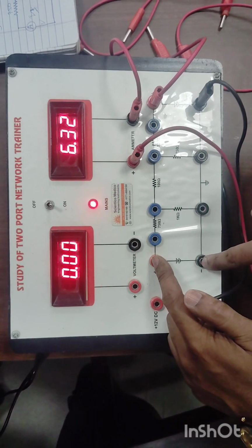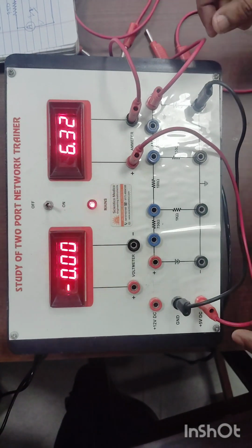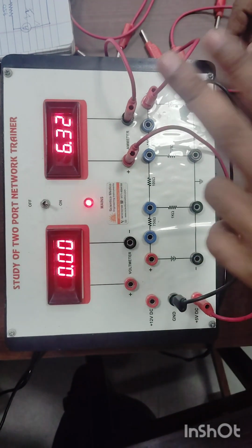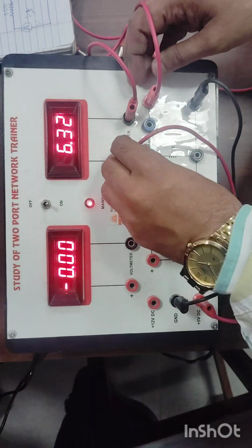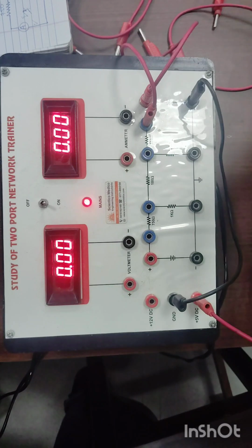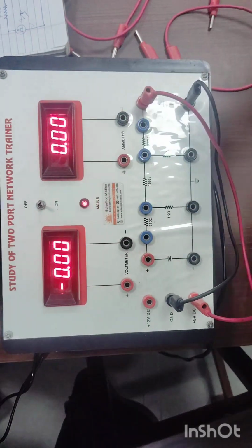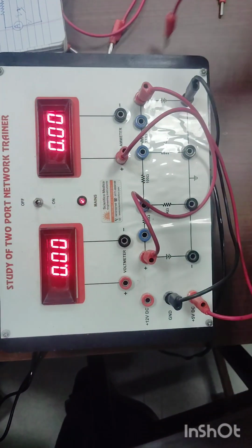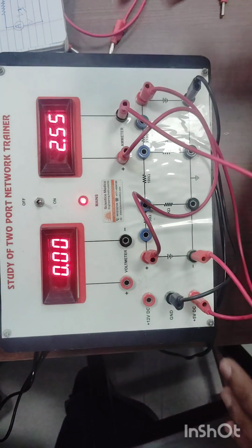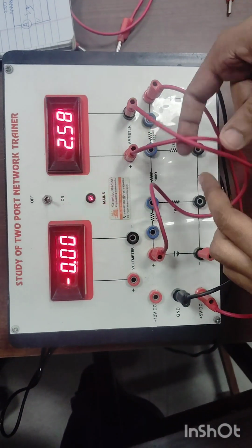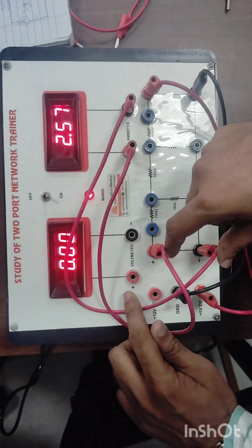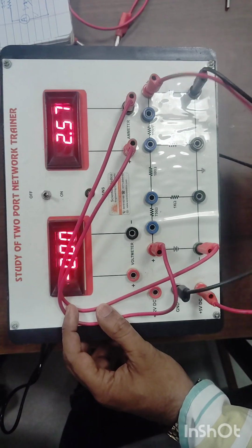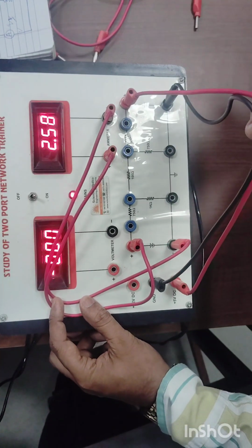And your last case is measuring the current across the AB terminal, because in the third case I1 is 0 since it is open, and in the fourth case we short circuit that terminal with the help of the ammeter. So here you can see, this is your ammeter and this is your I1. We have directly connected the AB terminal to the ammeter, and the supply terminal is connected here.